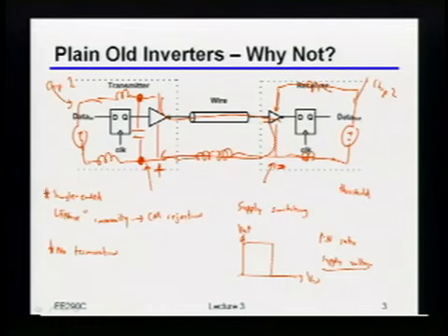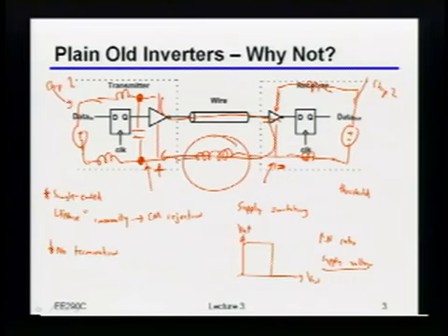Right? In other words, if you think of this like a cartoon, every time you have a transition, one of those chips is totally free to just bounce around like this. So if the on-chip supply is the distance between my fingers on the two sides, all the bypass cap does is make sure the distance between my fingers doesn't change. It says absolutely nothing about me doing this, right? Which, if you think about this nice big inductor here, I'm totally free to move that common mode, well, I called it common mode, I should really be careful. I'm totally free to move the ground on one chip completely separately from the ground on the other chip, okay?